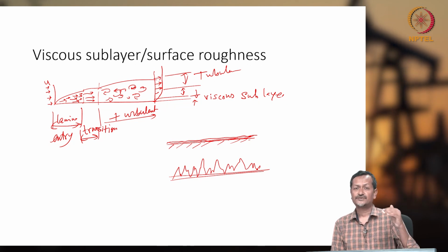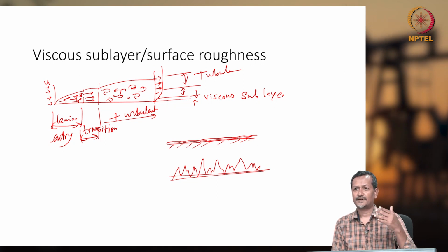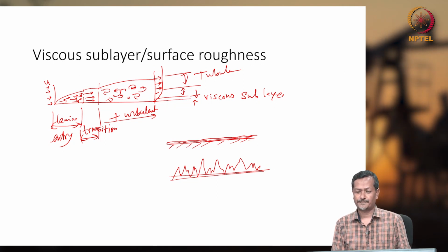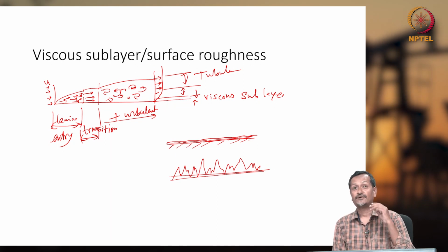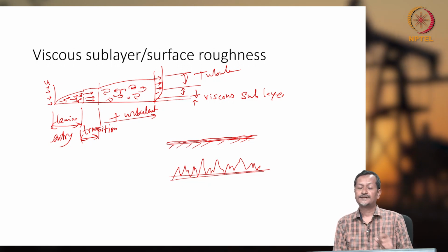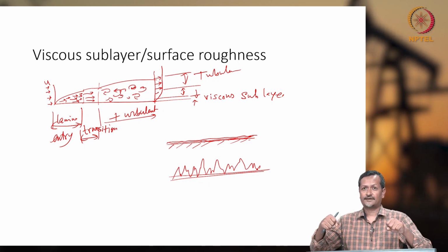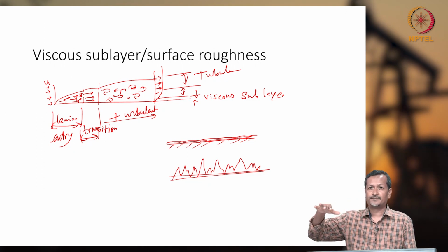The roughness will give more friction, and I can give one example of how roughness affects fluid velocity. Roughness will reduce your fluid velocity, it will give more resistance to flow, and the pressure drop will be higher. How? Let's say you have a bike and you're driving on a rural road, and the road is very uneven.